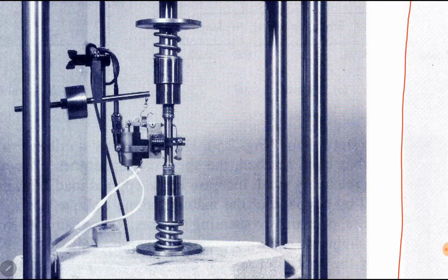HE is again known, it was given initially, 400 mm or 0.4 meters. And HD, which is X, has been found in the previous step. By putting in all the values, we can find delta E, the displacement of point E. Point E has displaced downward, so we have shown a downward sign here. It is 1.928 millimeters.